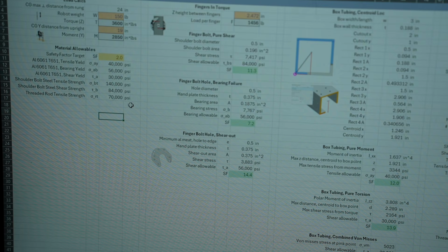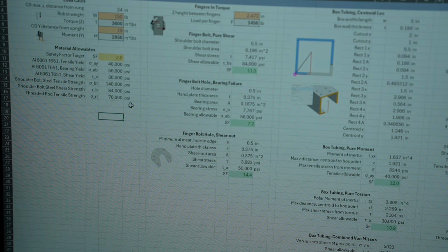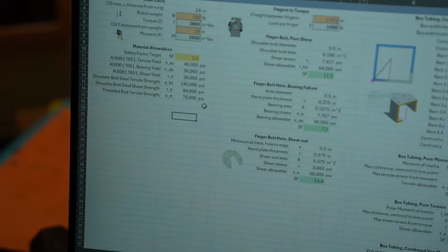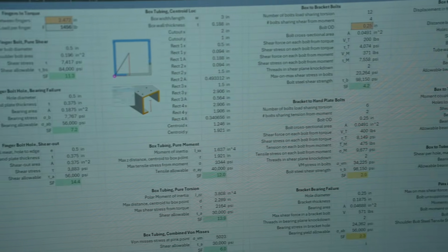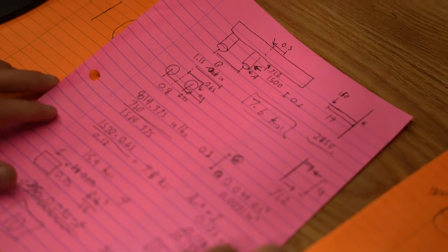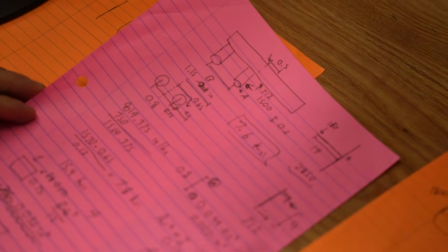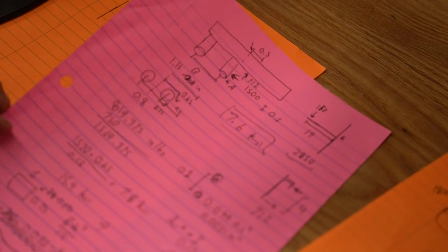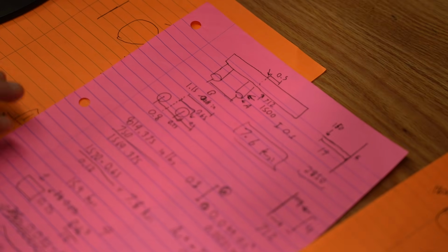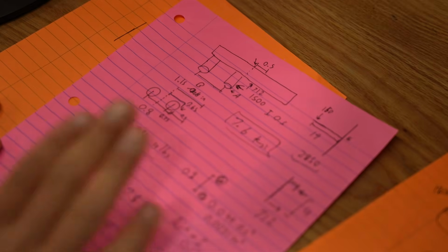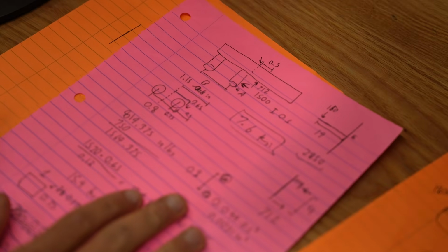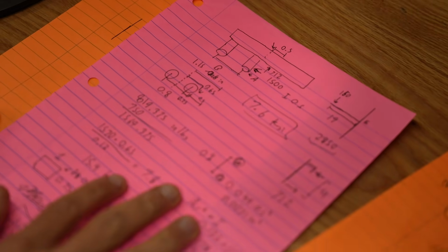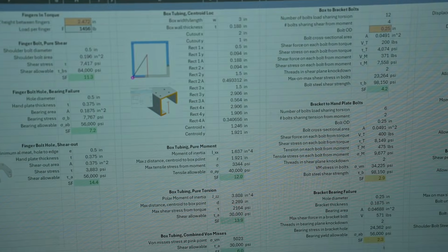Yeah. So if you're sizing something, like for one of these bolts, then guess and check from a graphing calculator is an absolute pain compared to guess and check in a spreadsheet. You can even have Excel guess and check for you using a function called goal seek. If we go back to this hook calculation, had I made an assumption error in the distance between these, I would have to redo all of this math in the same time it took me to do it the first time. So napkin math to bound your problem is great on paper, but as soon as you're doing more than that, I'd recommend moving to a computational solution.